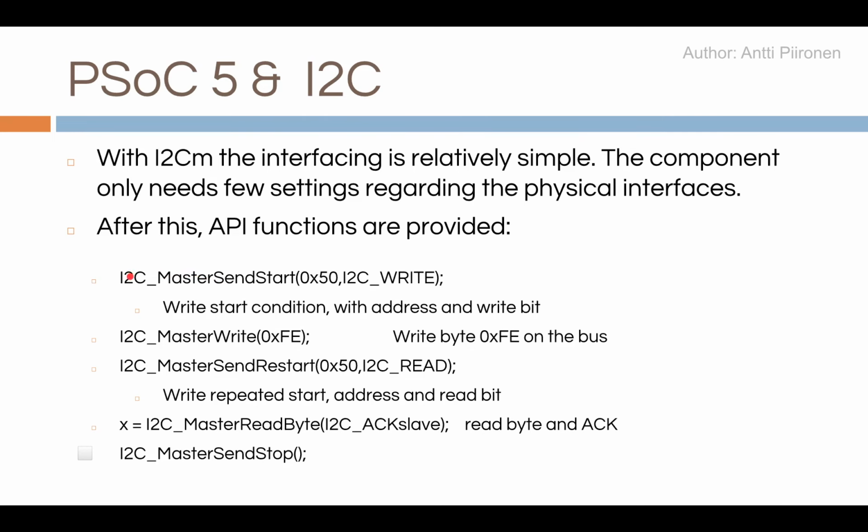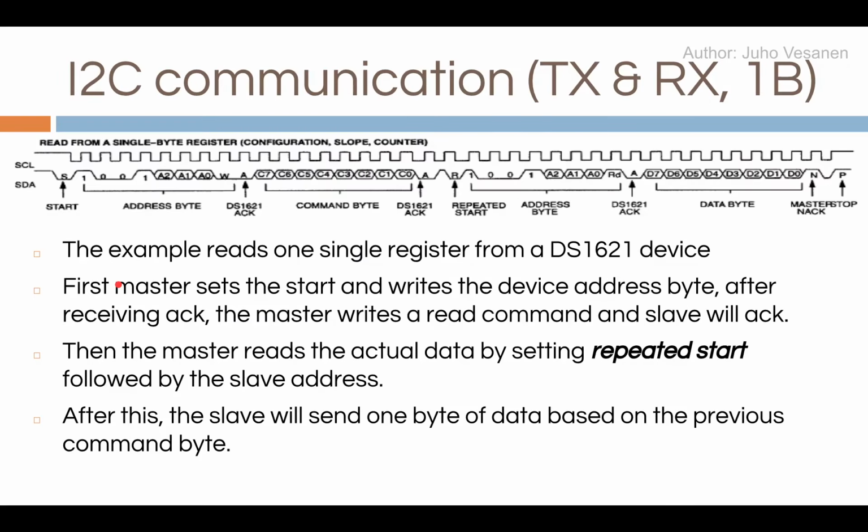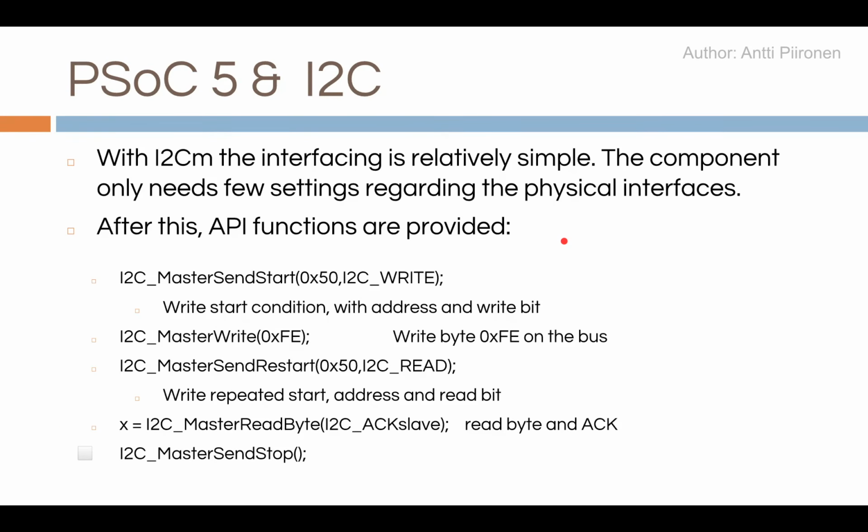So basically this is the same as we saw here, more or less. We have the start, setting the data in write mode with a command byte, then a repeated start and addressing the bus again with the read signal, and then reading the data from the device. So this actually does it.